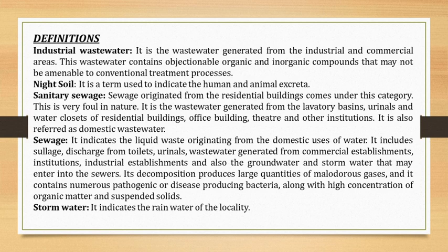So this is the collection of wastewater from the different industries and giving treatment to the effluent, and after that that effluent is discharged on the land or natural stream, river or lake as per the availability of the disposal point. Okay. So two terms are related here. The first one is ETP, that is effluent treatment plant, and the second term is CETP. Okay, so what is meant by ETP and what is meant by CETP? Okay, so before that we are going to discuss this term.